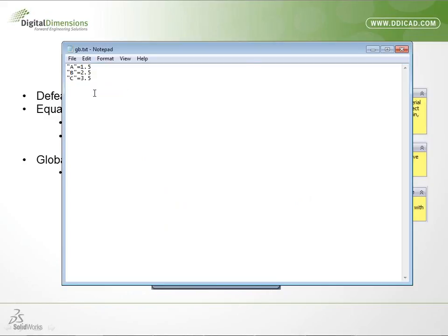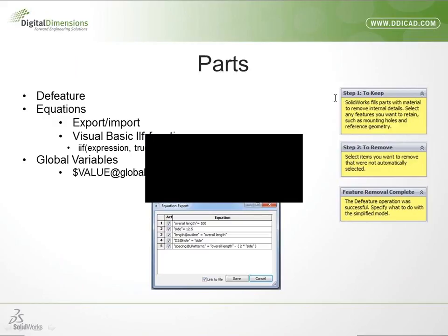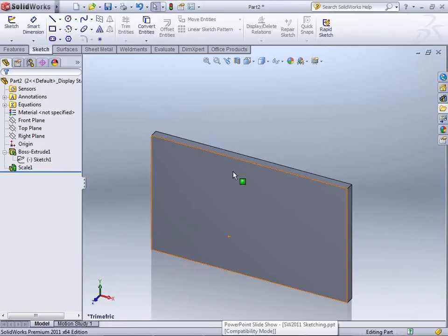So you can come ahead of time, define a bunch of global variables for a project or specific assembly. You're building 10 parts for this assembly, 100 parts for this assembly. You can set up all this stuff, and then all you have to do is just link to those things. So you link those dimensions to these global variables that exist in there. So, let's save this. Jump back over. Hopefully I'm making this clear enough here. Jump back over to my assembly.